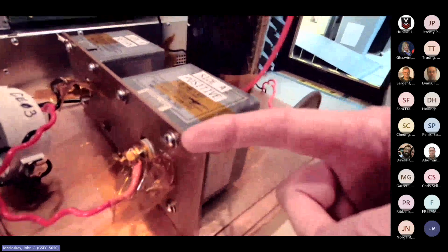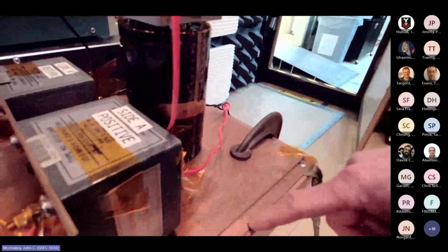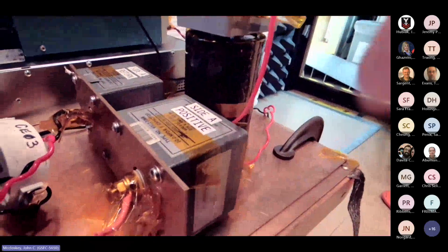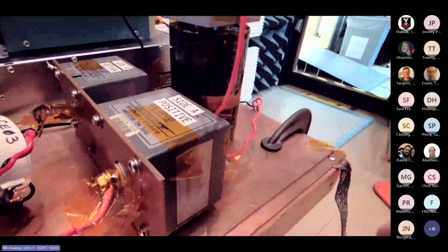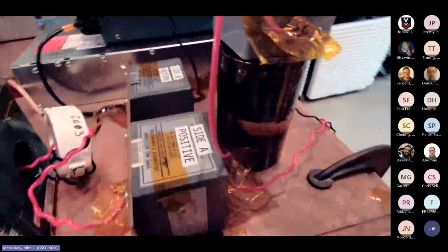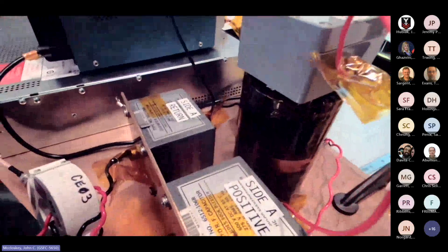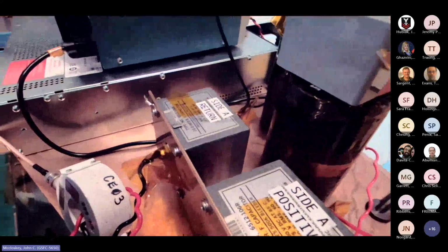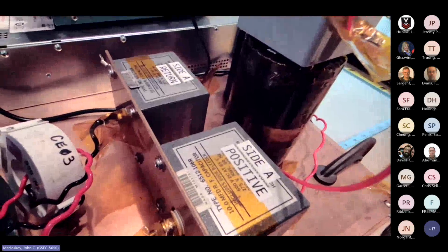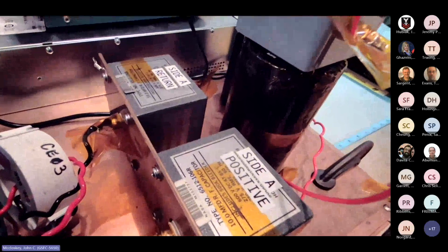Here we tied it to an L bracket, and then we clamp the L bracket to the ground plane. So that capacitance is to the common ground plane, and that is what was specified in the earlier days of the MIL standard, but that's at least a starting point toward getting us to a low source impedance that will simulate a battery.